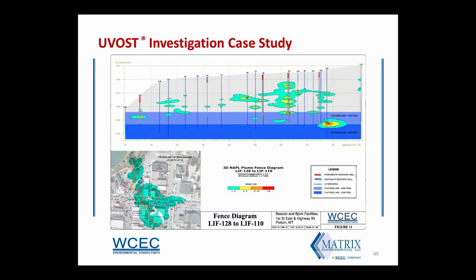So what did we do with our data? We used our data to determine a remedial strategy that is going to be installation of LNAPL recovery wells and eventual LNAPL transmissivity bail-down testing. We targeted areas of high concentration LNAPL or continuous larger LNAPL bodies for the installation of wells, and that work's going to be ongoing this winter and through the spring.